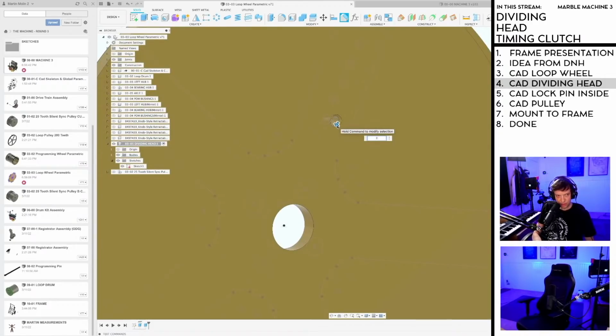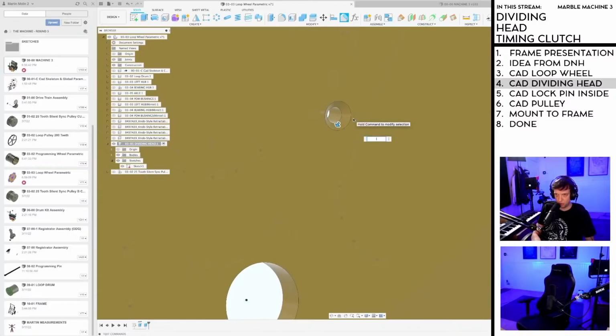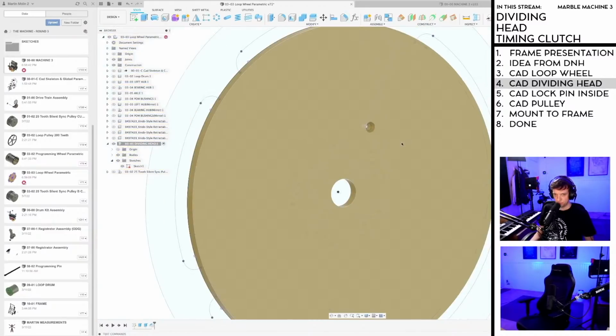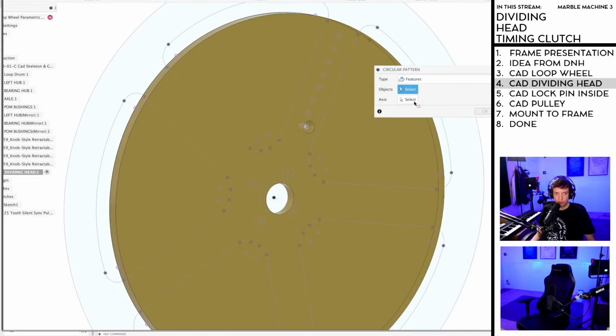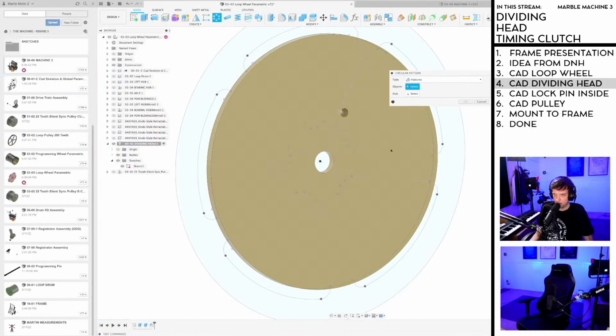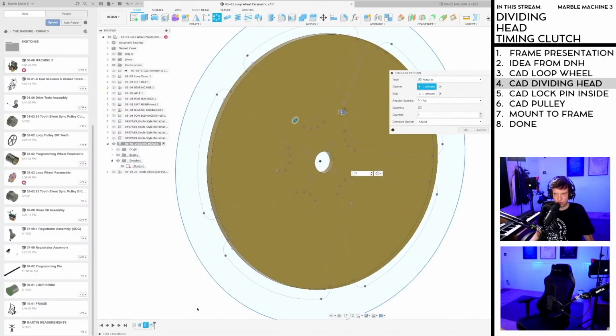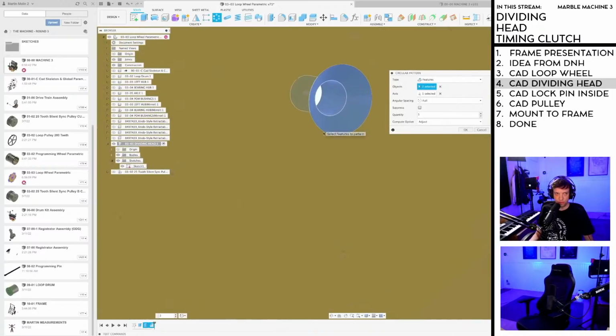So I'm going to chamfer this hole because we do not want anything sticking out for the countersink bolt. So let's say something like that. And here's the kicker. Now I'm going to make a circular pattern of a feature, which is much better for Fusion compared to making a lot of circular patterns inside the sketch. So I'm choosing this hole that I just cut. And I also want to choose a chamfer. So now I've chosen this.